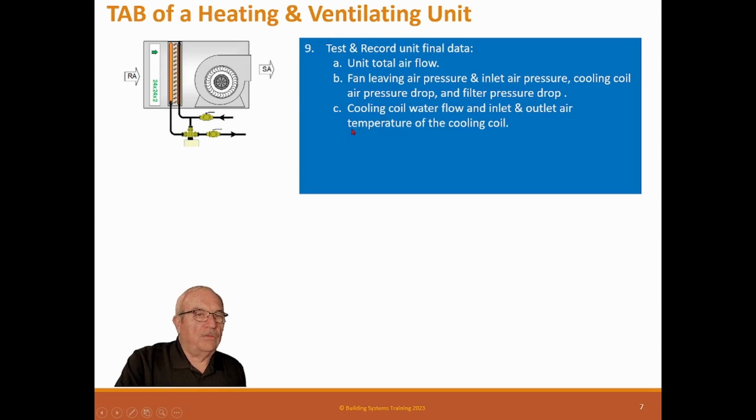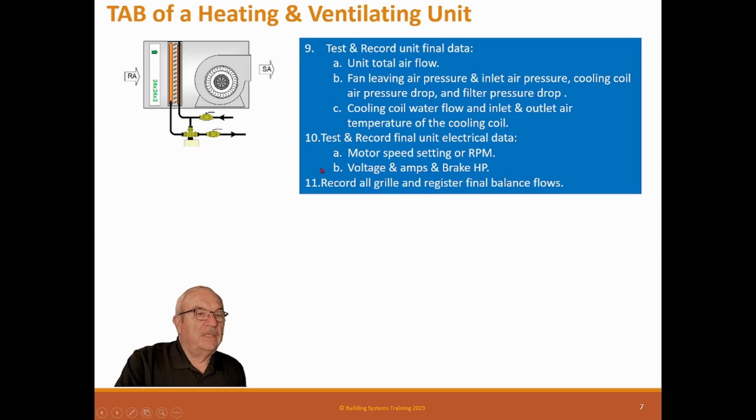Cooling coil, water flow, and inlet and outlet air temperature of the cooling coil. It's not a cooling coil, it's a heating coil, across the coil. Test and record final unit electrical data, which is motor speed setting or RPM, voltage and amps, and brake horsepower.